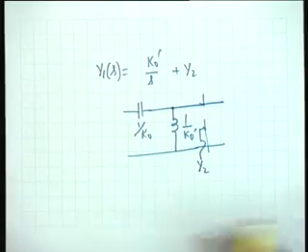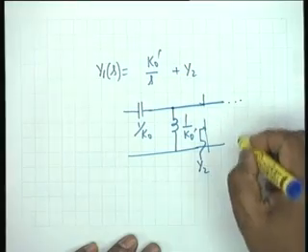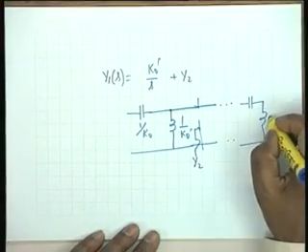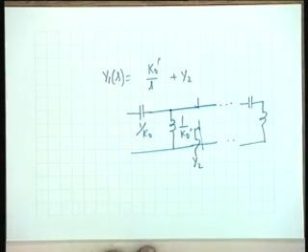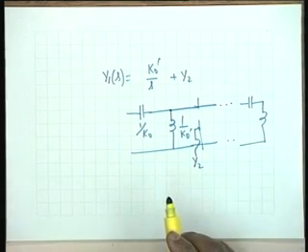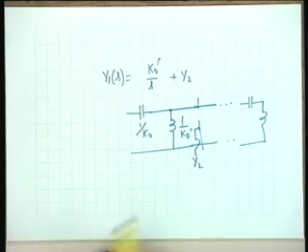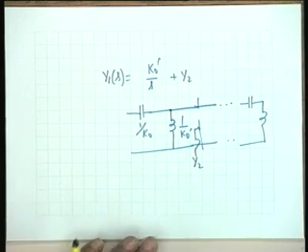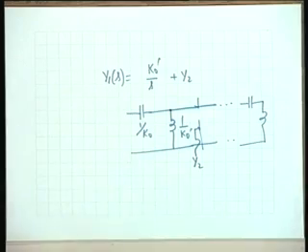And this process is repeated till we can proceed no further. In other words, we shall end up in an inductor. Once again, this will be the general form. Once again, you see it is a ladder. It is a ladder, but of a different kind, that is series capacitors and shunt inductors. Okay, series capacitor and shunt inductor. The first capacitor may or may not be present.